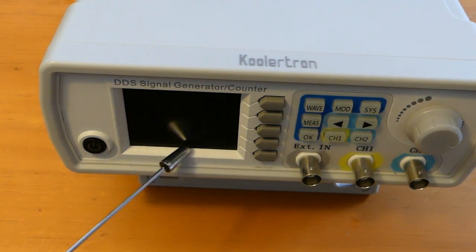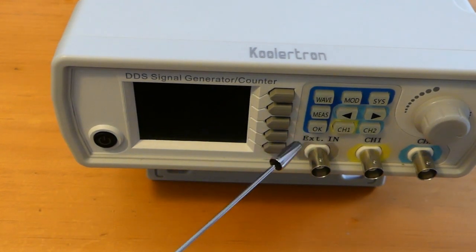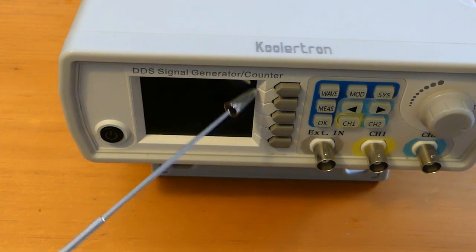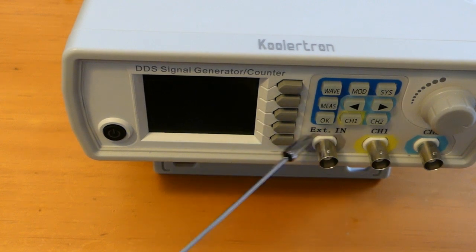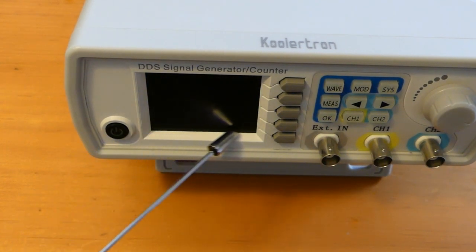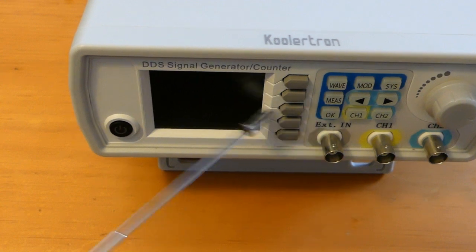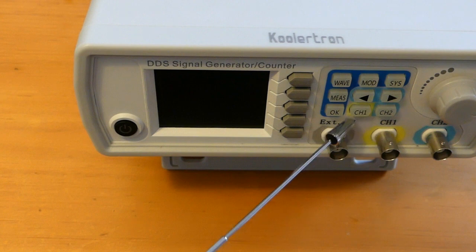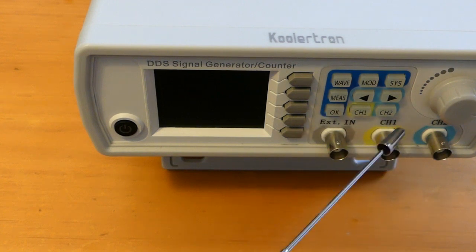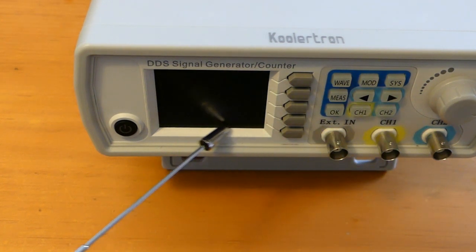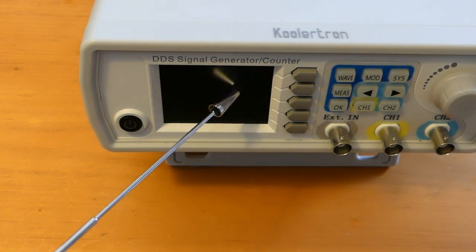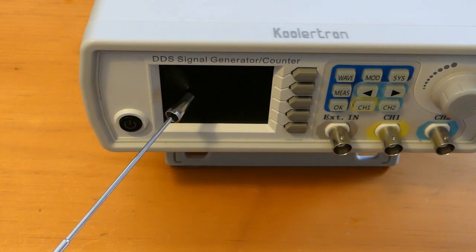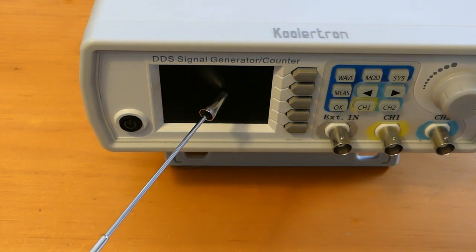Now, here's the real cheap Chinese signal generator. This is what we'll be using to make the LO. There are many of these. The FY9100 is a good one. If you want to stay under 20 megahertz or so, these things are easily under $100. So these are real cheap LOs, and these are what I use to make the LO. All we need is one port, so that's channel 1 there. When I'm showing my diagram that I want 7 dBm, you have to set the voltage peak to peak on this thing to be 3.2.